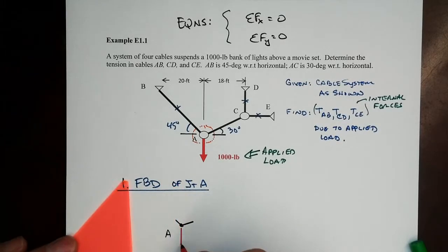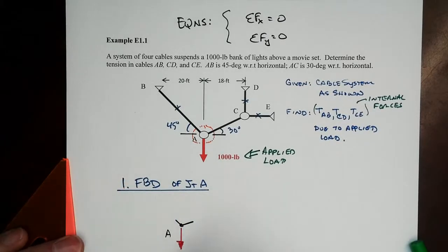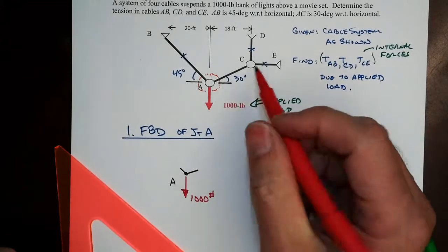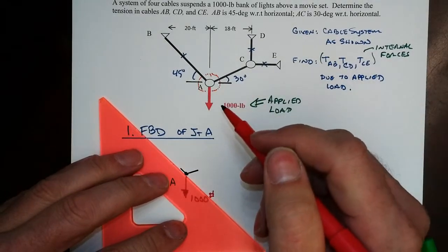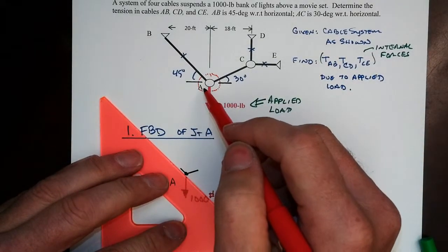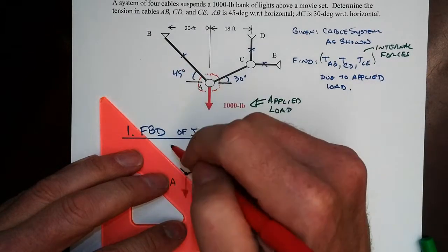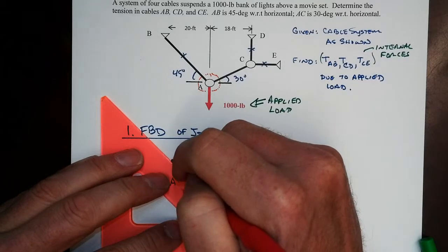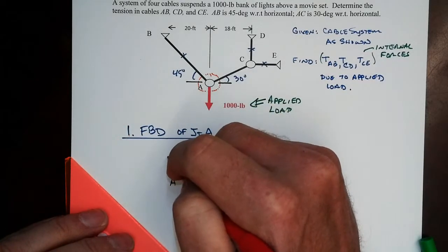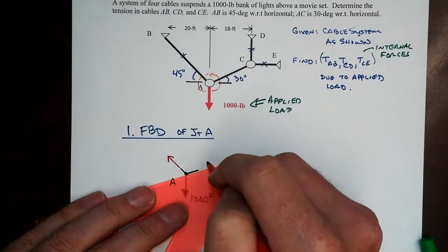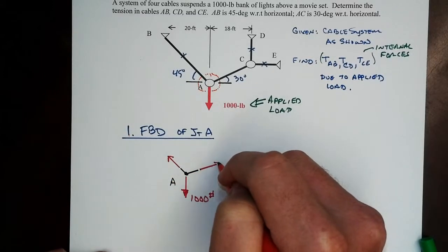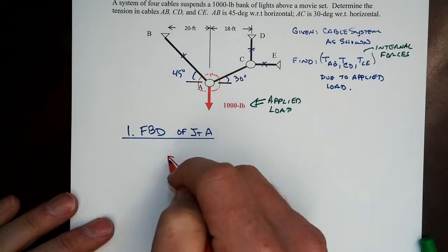And then we're going to show the force that we got here, also at 1,000 pounds. Right? That number symbol is also a symbol for pounds. Now remember, the line of action of the force is the same as the straight line between the 2 ends of the cable, especially for the work that we're going to do now. Later on we'll talk about how to handle the self-weight of the cable. Cables are in tension, so they're pulling away from the free body. Away, away, away.